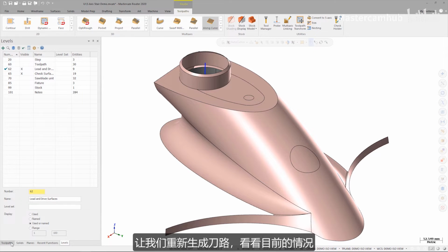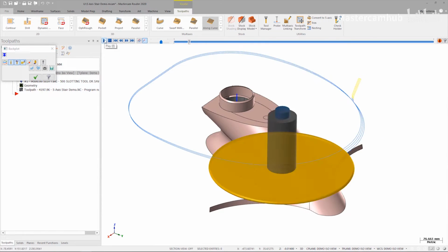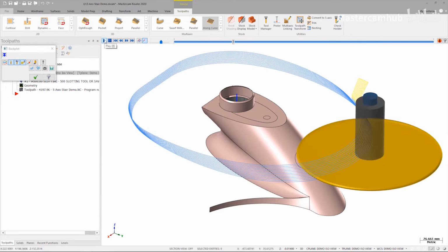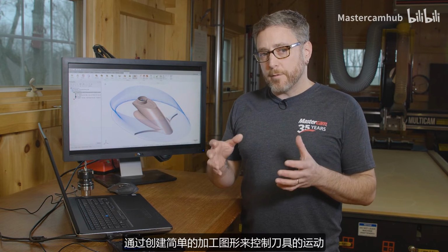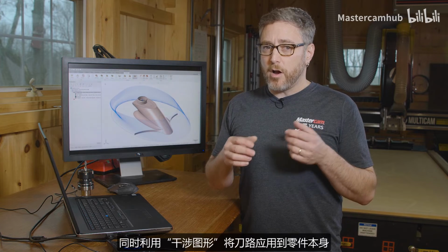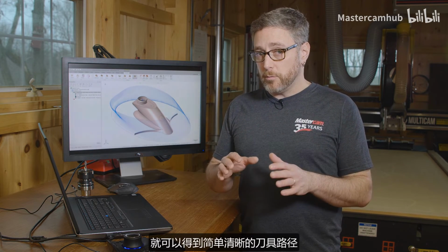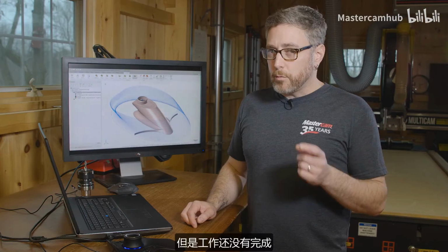Now let's generate the toolpath and see how it looks. By creating simple drive geometry to control the motion of the tool, while using the check geometry to offset the toolpath to the part itself, we have a clean and uniform toolpath. Now, this is going to result in less NC and a smoother, faster toolpath to cut at the machine. But we're not done yet.